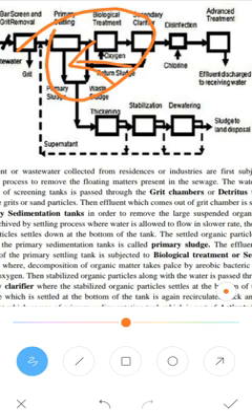The liquid which rests over the solid sludge particles and is removed out is called supernatant. After thickening and stabilization, the moisture content in the solid sludge is removed. That is the process of dewatering. The dry form of the sludge is used as a manure for improving the fertility of the soil.